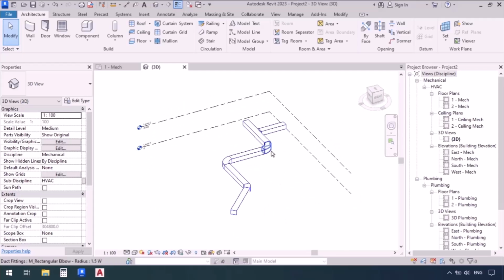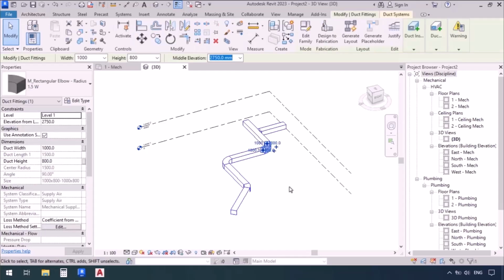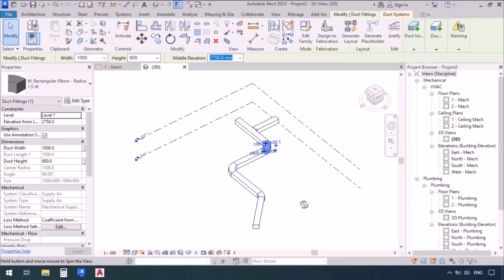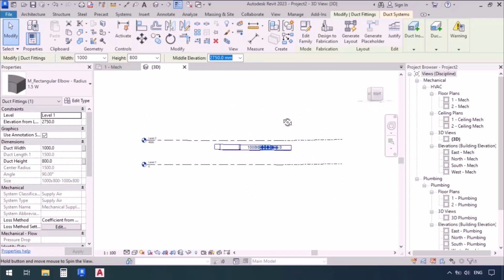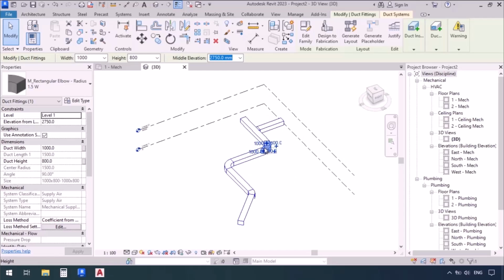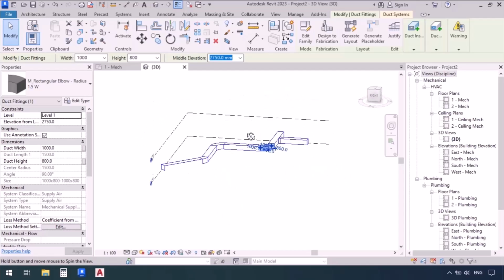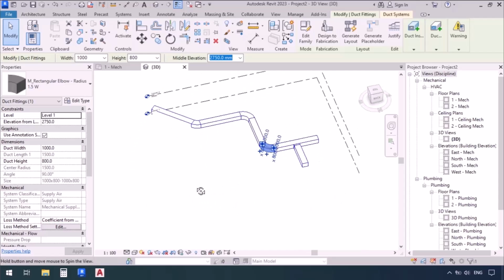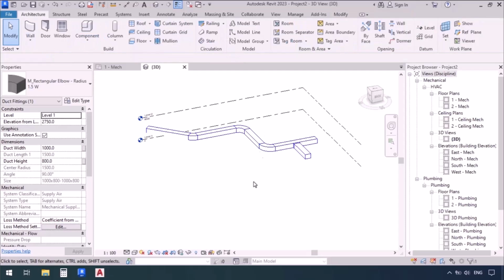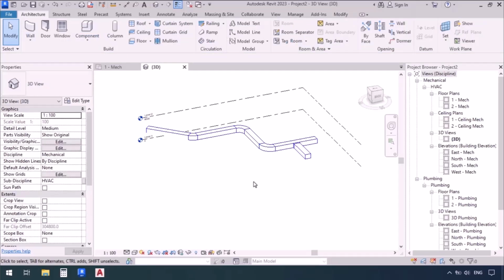Now, if I click on an item so it would be selected, and then do that rotating thing by holding the Shift key and clicking the scroll, with this selected item as the center, everything will rotate. As in, the center of my rotation would be this item right here, and all the other items will revolve around it. So I can rotate by the Shift key and the scroll key and see my model from different angles. This cube up here that we see, this one is called the View Cube or the 3D Cube.